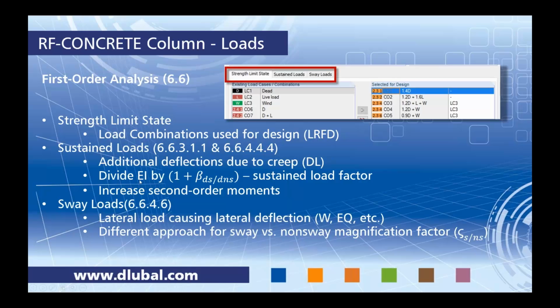And here we'll divide our stiffness EI by 1 plus the sustained load factor. In turn, this increases our second order moments done in the moment magnification procedure. So, like I said, if creep is something you want to consider, you will want to add that into the sustained loads tab.